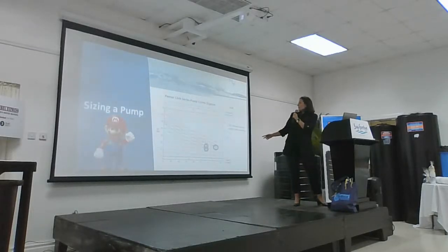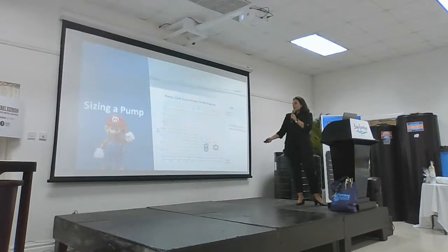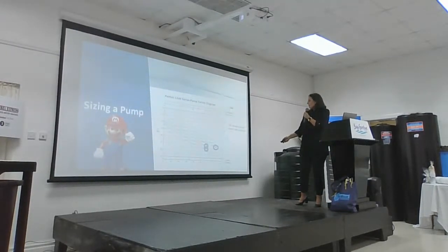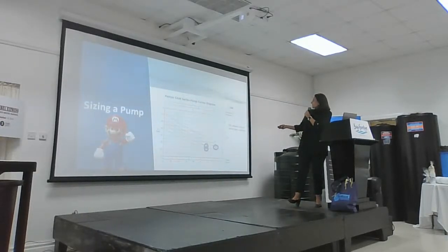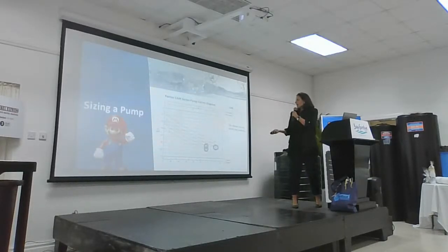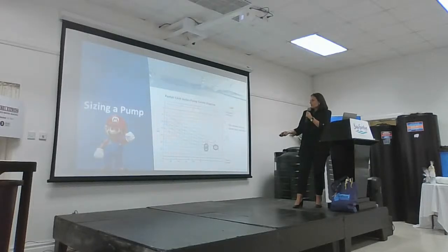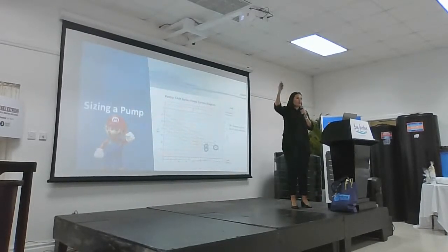So this is an example of a pump curve for a Pentax pump. On the y-axis, you can see we have height in meters, and on the x-axis we have the flow rates. We're going to be using the US GPM up here in our calculation for 1 GPM for each outlet, as well as the height, taking into consideration the height that the pump has to overcome.